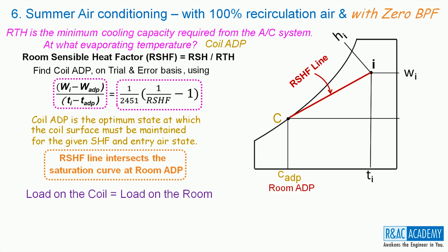Does it mean that the coil ADP and the room ADP are the same always? It need not be. It is the same in this case because the heat load on the coil and on the room are the same.